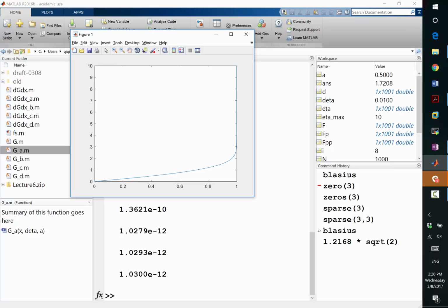Previously, we said that eta equal to 1 corresponds to 0.4, right? Now it corresponds to something a lot faster. The boundary layer got thinner. Thinner? Thinner, right. A positive A means the UE increases or decreases as a function of x? Increases. Yeah. What kind of pressure gradient do we have? Adverse. Favorable pressure gradient. It thins the boundary layer.